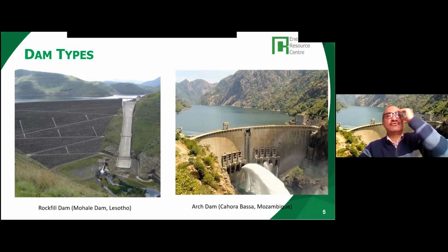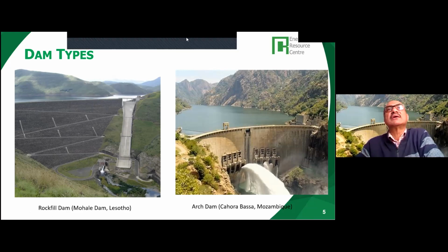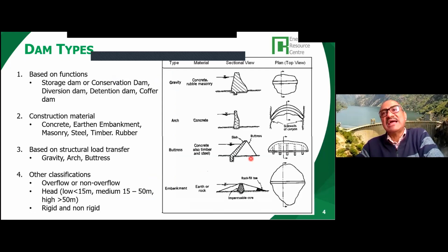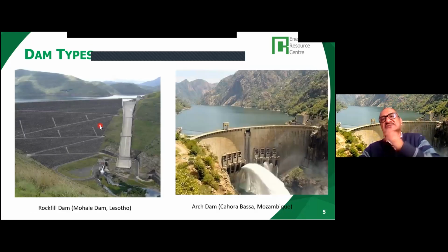One thing you have to be careful of is that in the earthen dam, the spillway cannot be part of the dam. So there was a possibility of having a spillway. This on the right here is the spillway. Okay, this is the spillway on the side over there. This is the rockfill. It's basically an embankment dam like this, but with rockfill, and there must be an impervious layer, earthen rock.